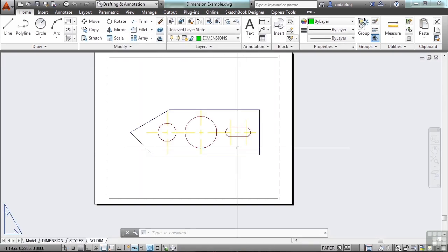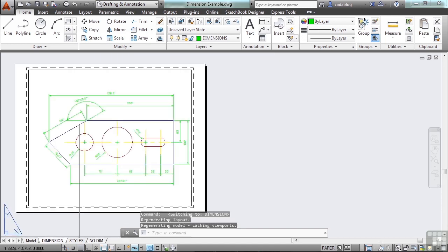You can create dimensions for a variety of object types in many orientations. Linear dimensions can be horizontal, vertical, aligned, rotated, a baseline, or a continued dimension, which is a chained dimension. Dimensions can be associative, non-associative, or exploded. Associative dimensions adjust to changes in the geometric objects that they measure. I recommend that you always use associated dimensions, especially if you are placing your dimensions in paper space. I'll show you some examples here.